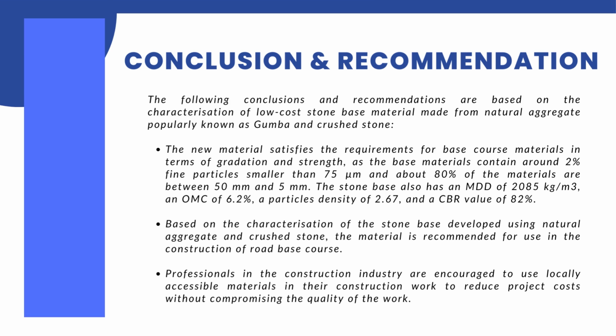As the conclusion and recommendation, it can be said that Gumba and crushed stones are a good and new material that satisfies the requirement for base course material in terms of gradation and strength, because the base material contains materials smaller than 75 mm, and about 80% of the material is between 50 mm and 5 mm. The MDD also improves, and the moisture content, particle density, and CBR also improve.